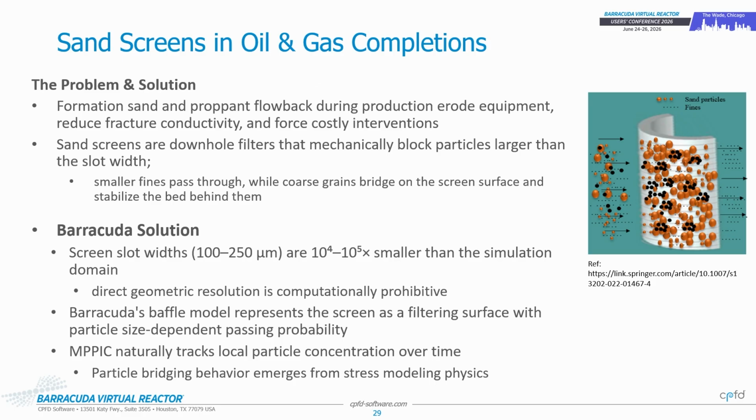Now, sand, liquid at high speeds is not a good thing, right? It essentially starts eroding away your metal equipment. And then, if you erode a lot of sand, sometimes you can collapse your rock formation. That leads to a complete loss of your well. Again, loss of well runs into millions of dollars.